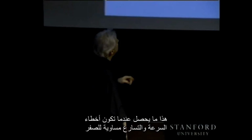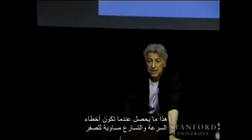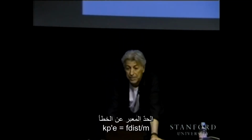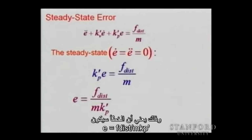So this is what happens when we have the velocity and acceleration errors equal to 0. And that means the last term, the error term Kp prime, is equal to F disturbance divided by M, and that means your error is going to be the disturbance force divided by M Kp prime.